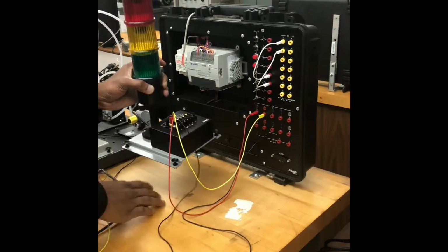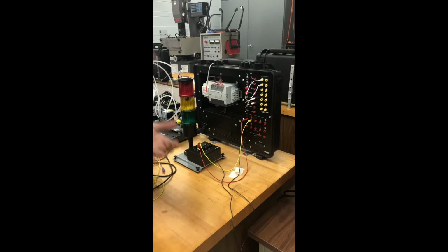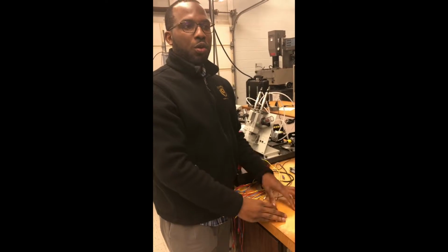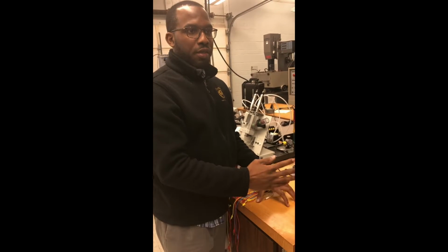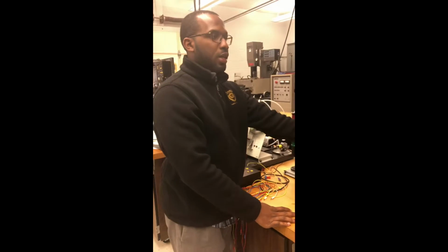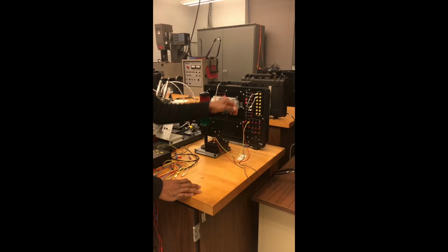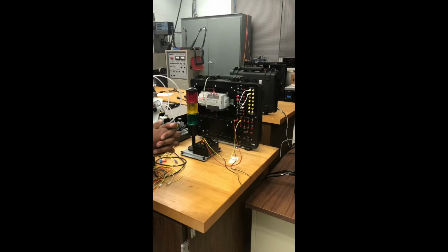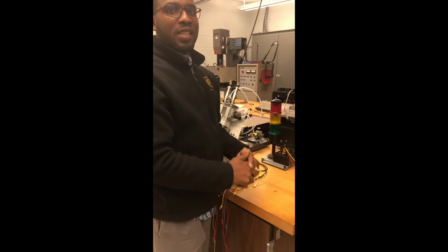Okay, so the PLC involves three things. First, we need to draw the diagram. We can draw it on paper, that's fine. Then we go on Automation Studio and connect the circuit and create the PLC logic. So the first step now is to put the PLC program using RSLogix in the computer, and then also connect the circuit physically with the PLC and test it to make sure it works as you designed it to work. And these are the steps that are involved. So I hope you can take these instructions and complete your lab number 1.